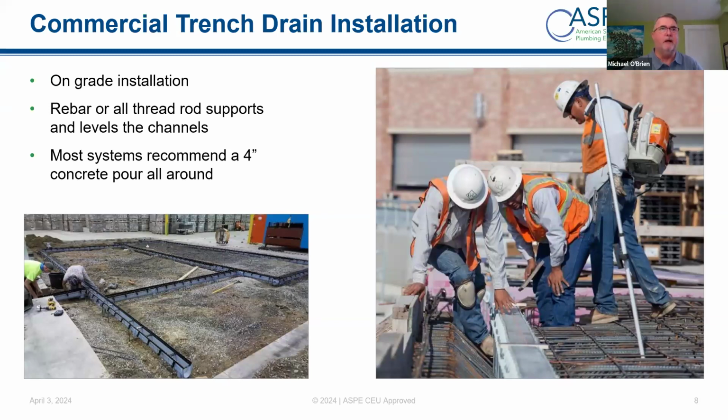They use things like rebar and threaded rod supports to level the channels. In the case here where it's a wide open pit, they would use rebar and channel. But if they're, say, retrofitting, they could cut out a section of the floor that's a good amount wider than the trench drain they're trying to install, and then support it with something like unistrut across the opening and down from the top.